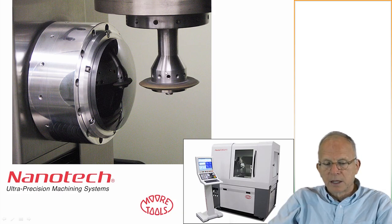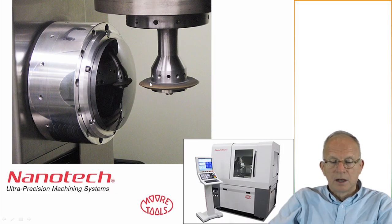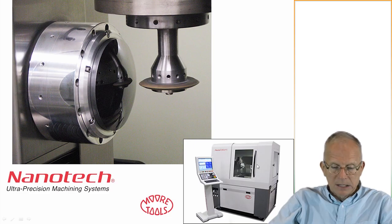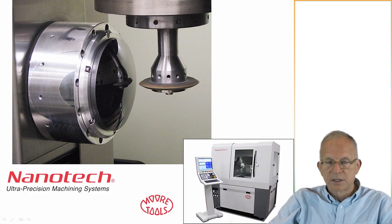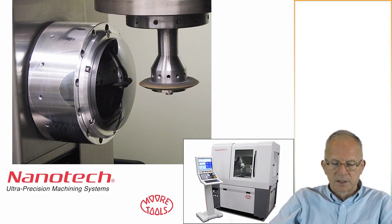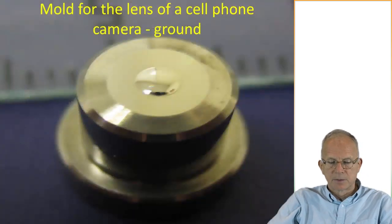So here's a grinding head on this, and here's a ground surface, and you can quite easily see the reflection there. So you can make surfaces that are very smooth and very precise with this. And this is the kind of machine that is used to make the molds to make the aspheric lenses that go in cell phone cameras, for example.